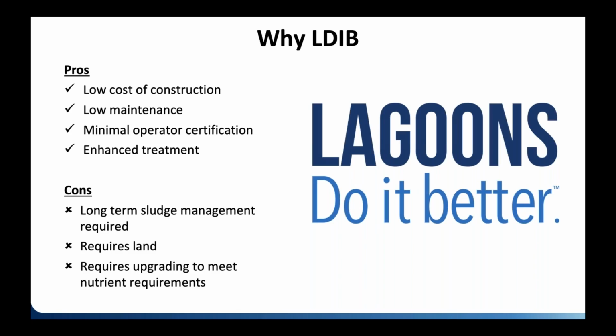So lagoons do it better because they have low construction costs, low maintenance, minimal operator certification, and you can treat now to these new nutrient standards if you have the equipment in place. Downside is you do have to manage sludge in the long term. You have to hire a contractor. It's going to cost you $1 million or a lot of money to remove all the sludge in your lagoon system, but you need to budget for that. It does require land. And if you do need to meet those nutrient limits, you have to upgrade your lagoon system.